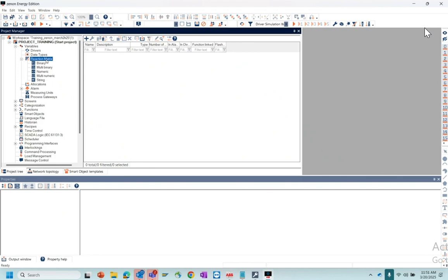Mainly this will be used during your alarms. We know that in alarms, in bool, it's either true or false. In integer, you will set ranges, right? In that case, for alarm handling, for better understanding, you can use this reaction matrix and set colors for different limit levels, temperature limit or pressure limit, like that. Valve open, valve close, like that.